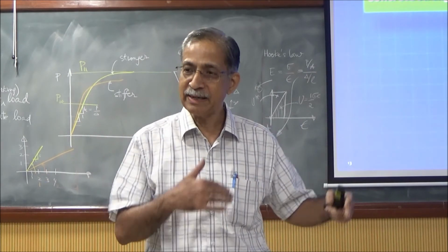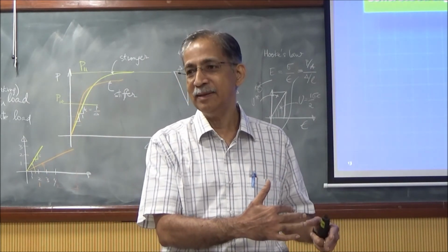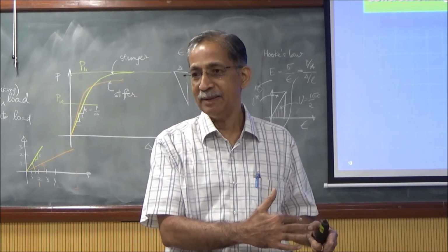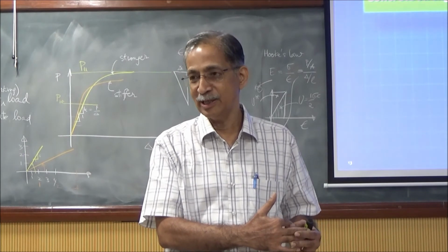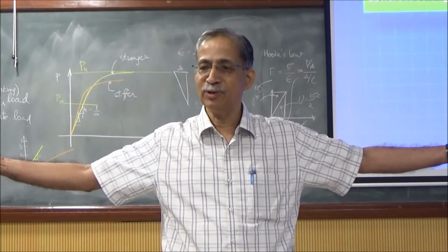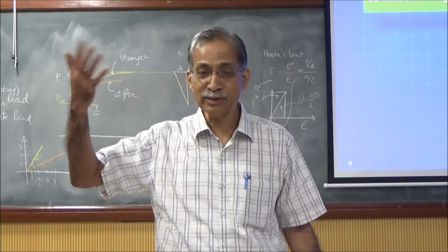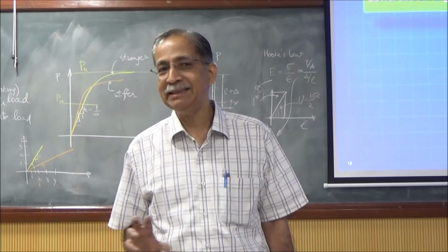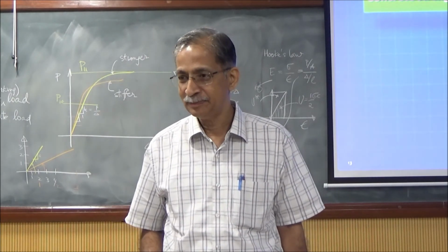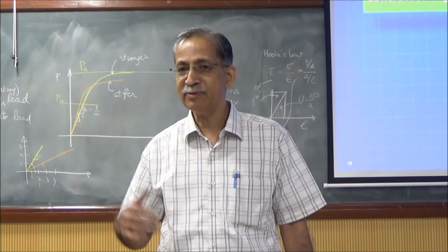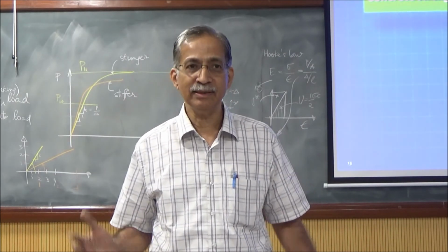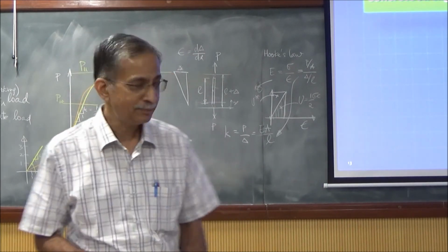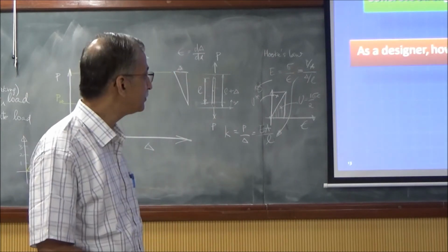Okay, and the code gives some numbers, but still you have to use your judgment. It all depends on the size of the volume, and the importance of the structure that you're going to build. So it's not an easy answer. 3 is the absolute minimum for convenience. But sometimes you have to test 30, sometimes you have to test 100. It depends on the specific application. Yeah? Any other questions? These are good questions to ask.